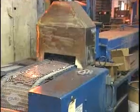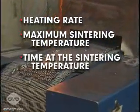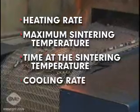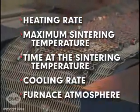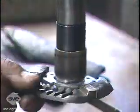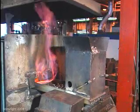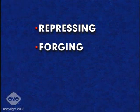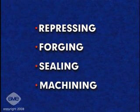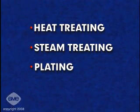To ensure proper sintering, the heating rate, maximum sintering temperature, time at the sintering temperature, cooling rate, and furnace atmosphere must be closely controlled. After sintering, parts may require additional processing in secondary operations to achieve net shape and/or meet performance requirements. Secondary operations include repressing, forging, sealing, machining, heat treating, steam treating, plating, and joining.